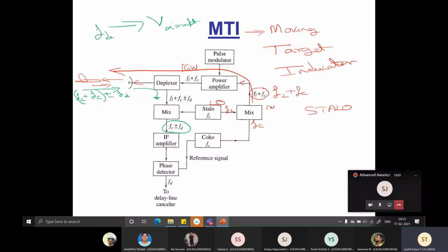If I remember right, in radars the intermediate frequency is around 50 megahertz. It is just a standard. All radar devices came out like a communication receiver, where we have 10.7 megahertz and 455 kilohertz. Radars generally have these 50 megahertz components.